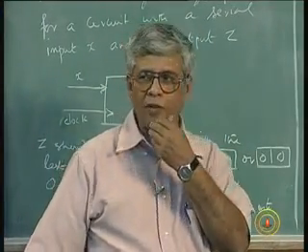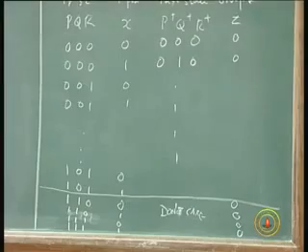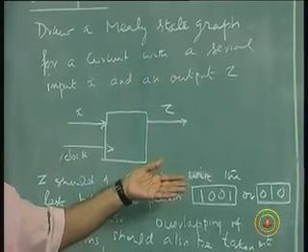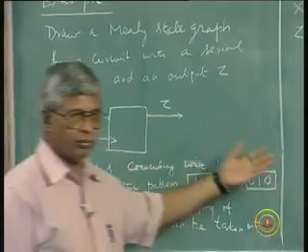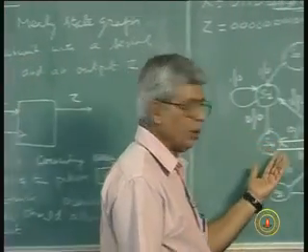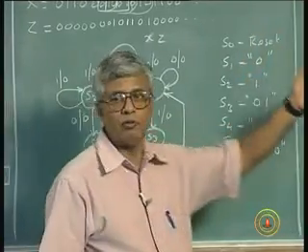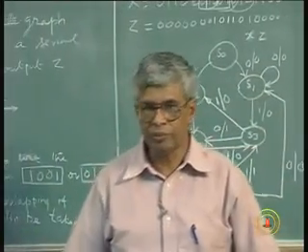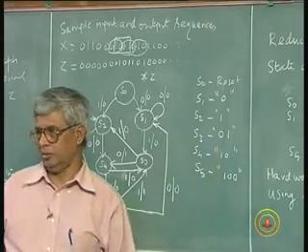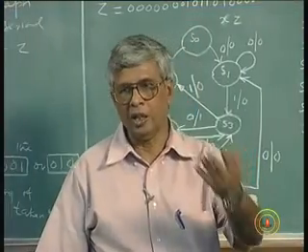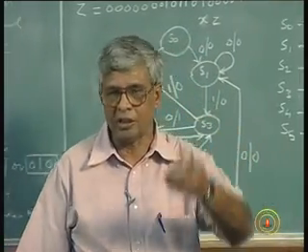So this is how you start from a basic problem definition with very clearly stated specs. Take all possibilities into account, draw the state graph. From the state graph, you do the state assignment, reduce the states if necessary and if possible. Do a state assignment either randomly or arbitrarily or using some thumb rules or design rules to make it efficient.